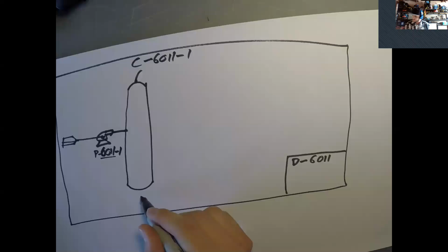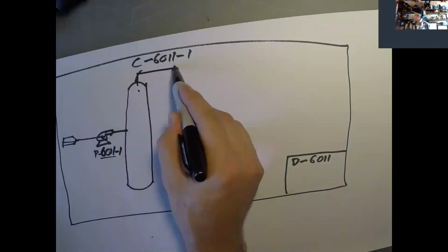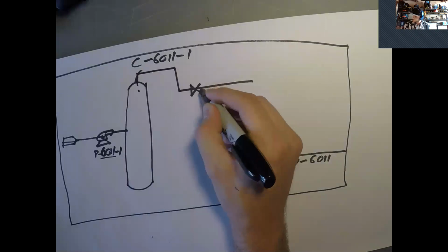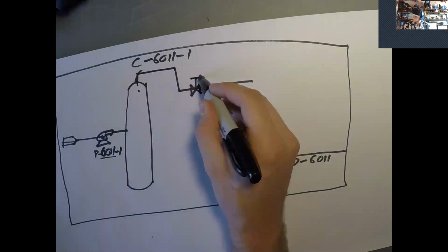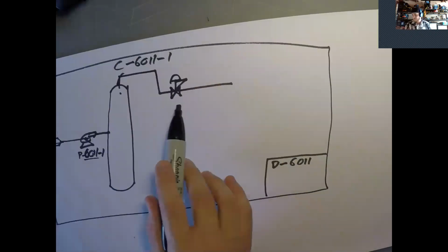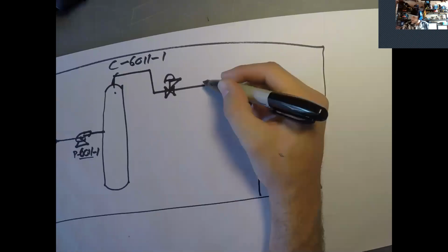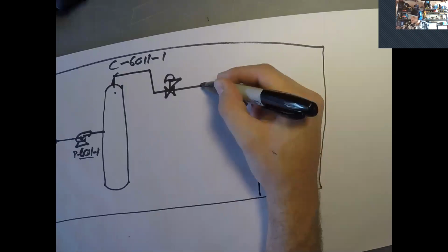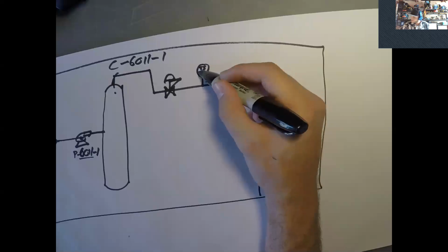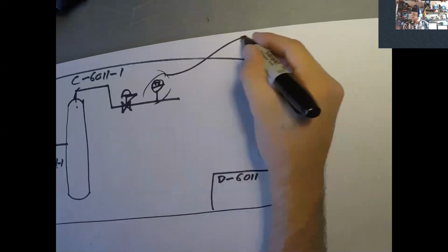The other key aspect of this is the instrumentation. So let's say you have a tops stream from here. You might control that flow rate with a valve. And so this symbol, this is a regulator valve. So that basically controls the downstream pressure here. You might have a temperature probe on here. Oof, that's bad. Okay, I'm gonna blow that up. Apologies for my bad handwriting.